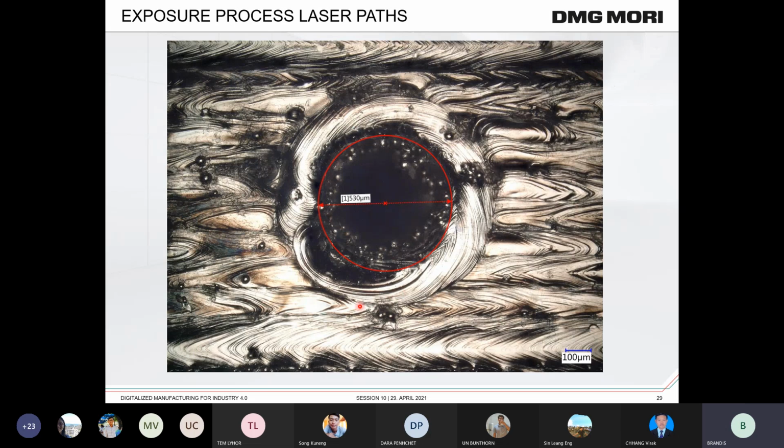And interesting is where you can see these small areas, small particles. These are powder particles that are not melted, so they glue together or sinter together. It's not possible to remove them with a vacuum cleaner, but normally we use sandblasting or blasting with glass pearls to remove all these particles on the surface. This works very well.